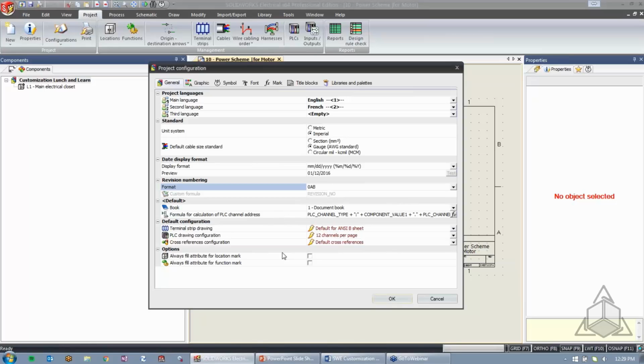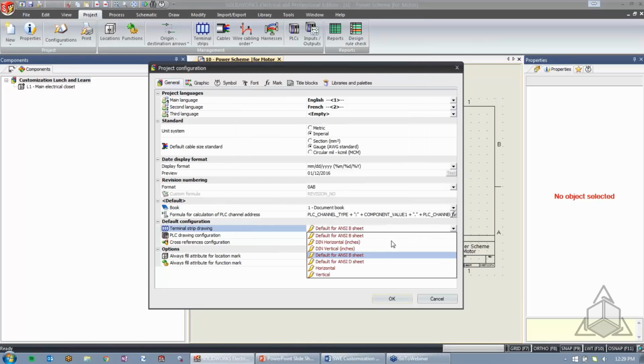All right. Down at the bottom of the page, we have our default setups. So what is our default configs that we want to use for PLC numbering, our PLC creation? So when we make a PLC drawing or a terminal strip drawing, what documents do we want to use? And we can see that we have some application level settings set up right now. We can always go through and actually search for all our various setups in our terminal block drawings or in our PLC drawings.